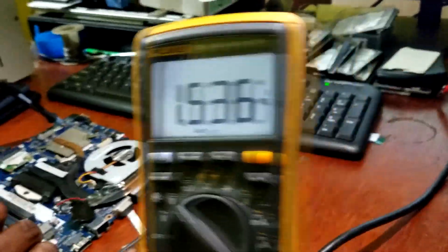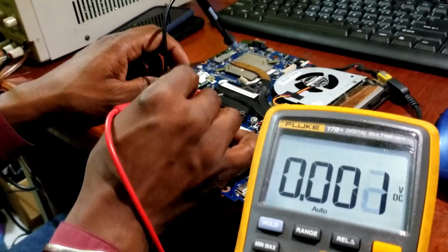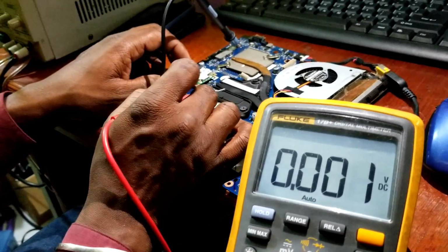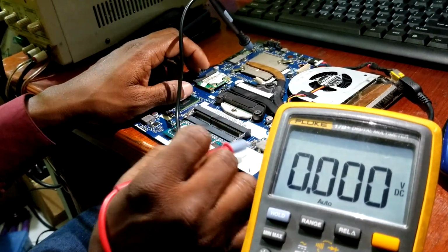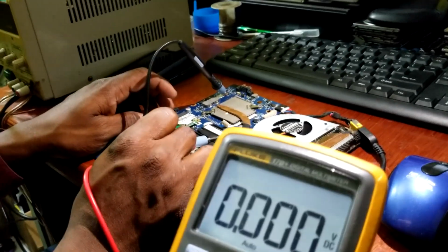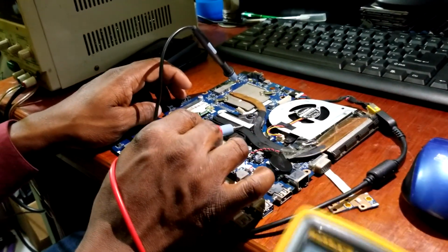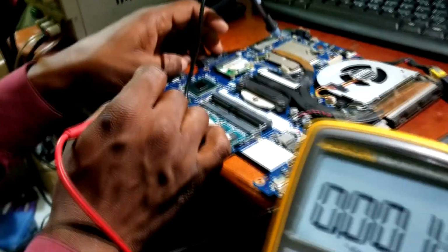Measure. As you can see, this is 1.5 volt. This is RAM supply, right? And this is powering the RAM and the VDDQ RAM section inside of the CPU, right? This voltage is going to the RAM slots, and it's also going to the VDDQ module inside of the CPU, right? Very important. So once the CPU working condition is okay, then the BIOS